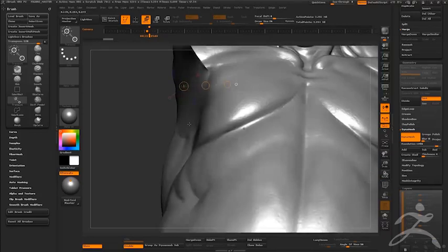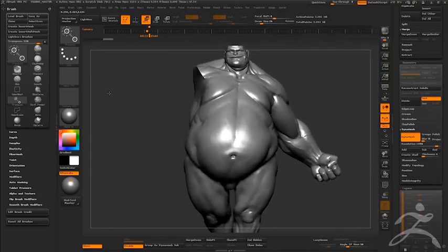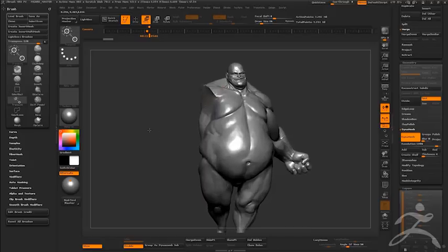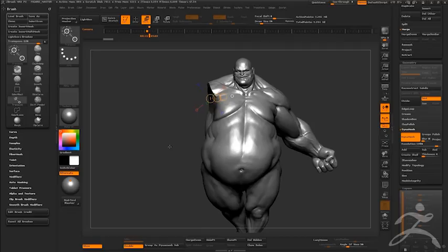Now, for animation, obviously that's not good. You're not ever going to create anything that dense in something like AutoCAD or Rhino. But that's the beauty of ZBrush: poly count doesn't matter. Because when you get to a certain point, right before you're ready to send this off to the printer, they have a really nice decimation plugin. Again, the most powerful I've ever used. You can crunch this 3 million, this eventually is going to end up being 7 million, down to about 400,000 points, with absolutely no loss of detail.